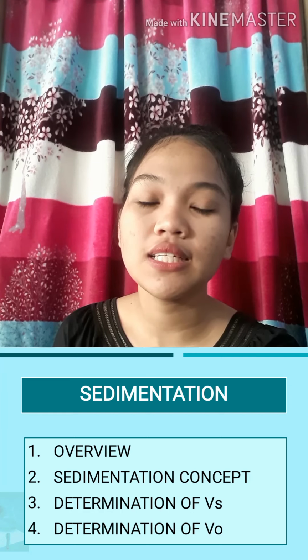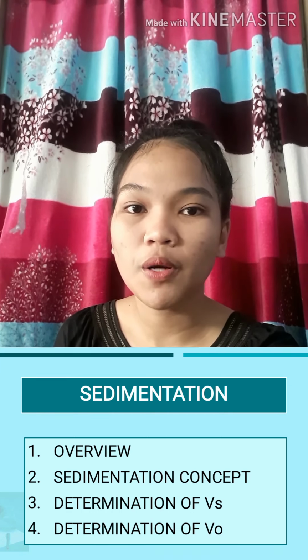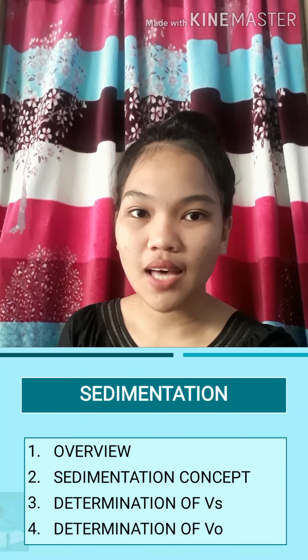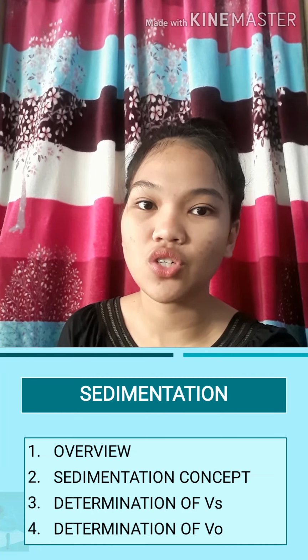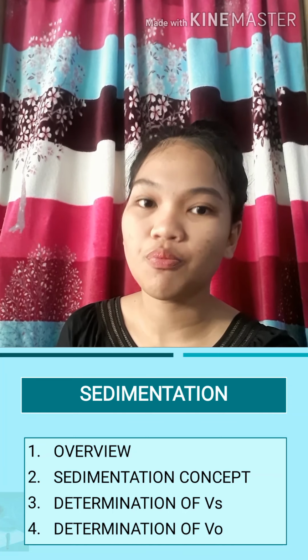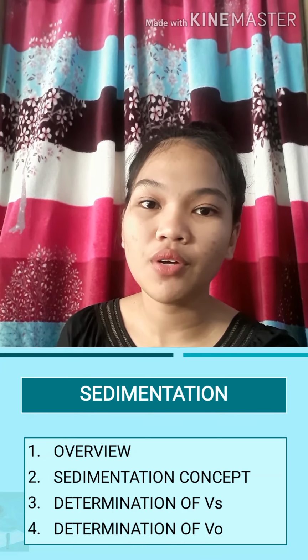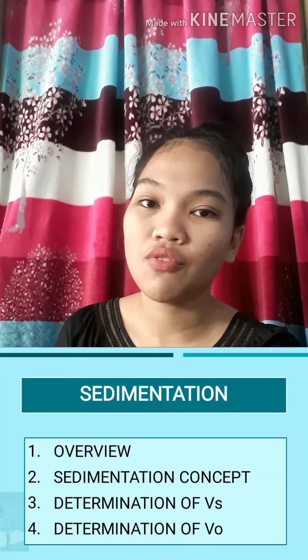Now, for the second sedimentation, or type 2 sedimentation, it is characterized by particles that flocculate during sedimentation. Because they flocculate, their size is constantly changing. Therefore, the settling velocity is changing as well. Generally, the settling velocity is increasing. This type of particle occurs in alum and iron coagulation, in primary sedimentation, and in settling tanks in trickling filtration.